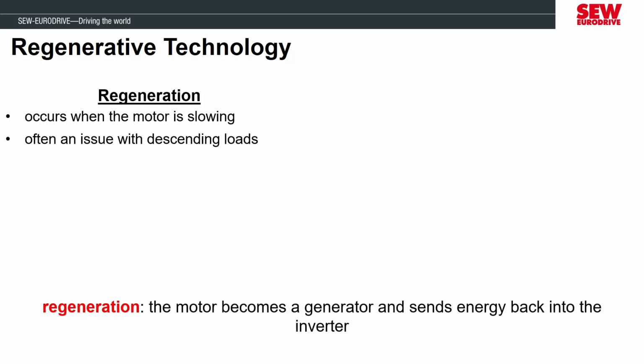In these scenarios, the motor changes from being a consumer of energy to being a producer of energy. The energy has to flow somewhere, so it goes backwards towards the inverter and starts charging the DC link above its steady level at 700 volts. The DC link capacitors have limits around 1000 volts, so if the charge level reaches this point, the inverter has to have another place to continue sending the excess energy.